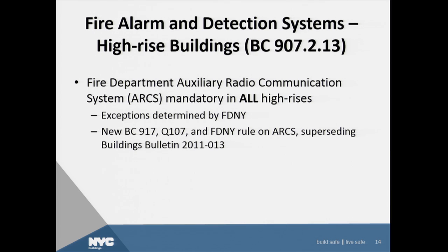Okay, so now ARCs. You'll hear the fire department talk about ARCs. Auxiliary radio communication systems. These will allow the radios to repeat through the buildings. The requirement is that they be provided in the high-rise buildings. The fire department is working out their rules and how that's going to happen. They had issued a technical management bulletin on this explaining how that is to be designed. They are revising that, so I urge you, if you're designing high-rise buildings, if you are the fire protection engineer and you're dealing with these kinds of things, to understand what that means for your projects and follow up with the fire department on it. I've listed here the code sections that point you to it, and there you go.